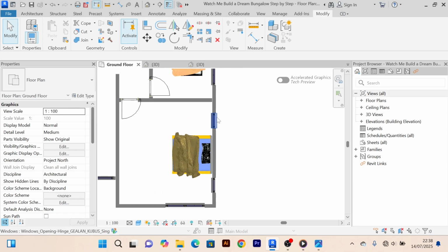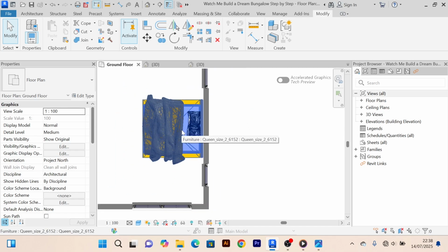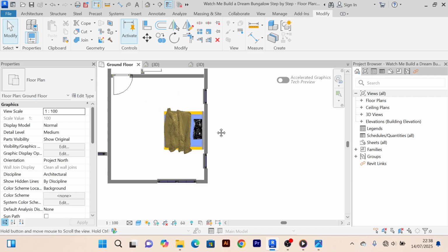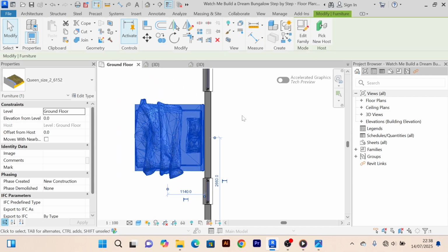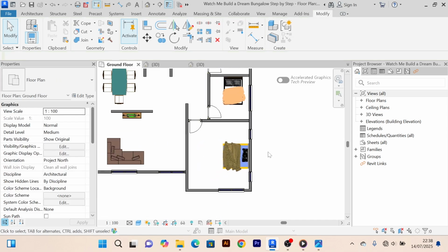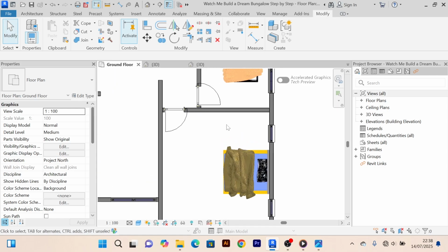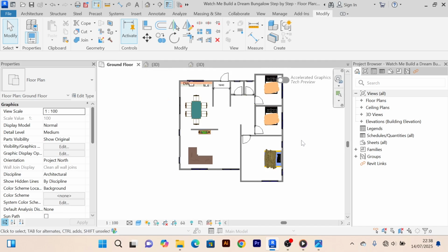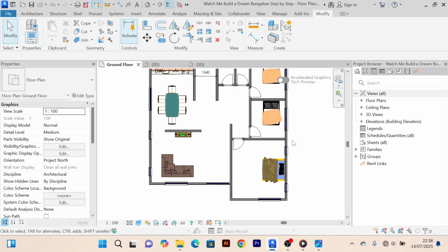And if your bed is directly facing these openings, it can affect your comfort in your own room. So for that matter, you should always avoid having the beds facing the openings directly. And even for security reasons, it's not advisable for your head to be directly where the openings are. So that's basically the reason why I'm putting the beds towards the walls, not the openings.